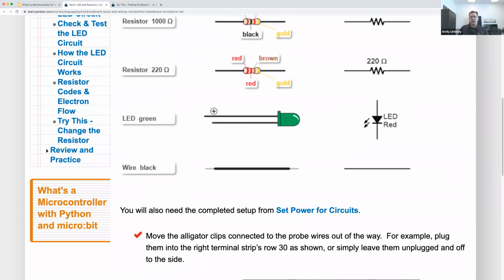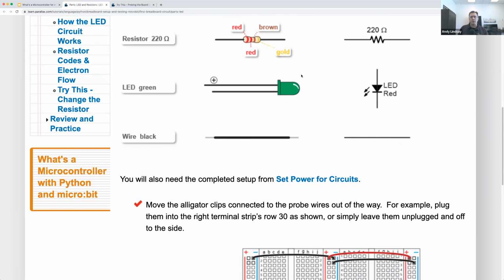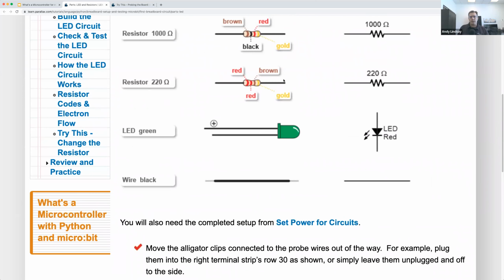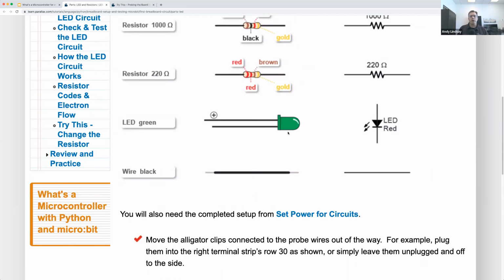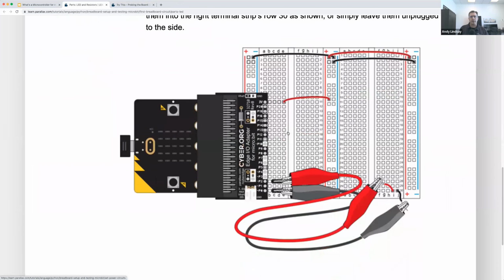Resistors, incidentally, are not. The light emitting diode is a directional device. If you plug it in backwards and apply voltage, it won't give off light. You can unplug it, plug it in forwards, then it gives off light. And the resistor, current will flow through it either way. An LED is a one-way valve, but I'm getting ahead of myself because that comes later.